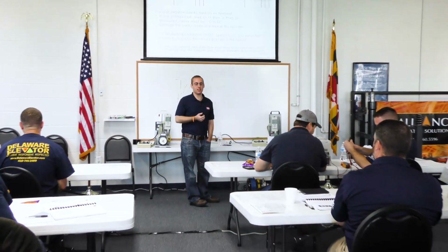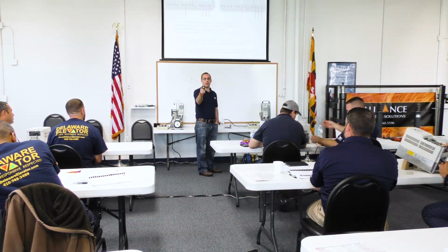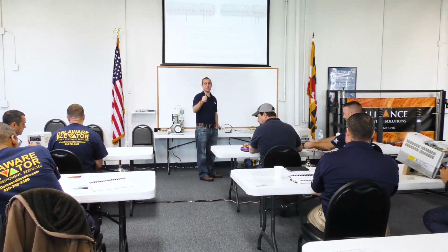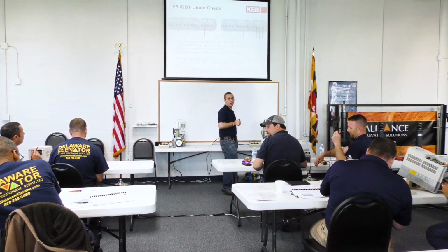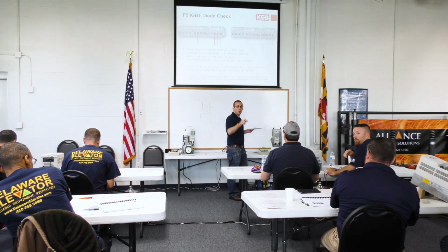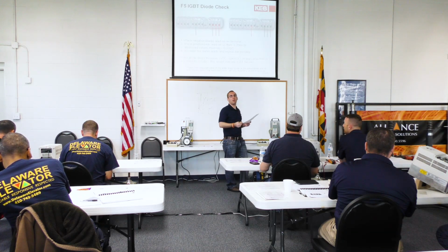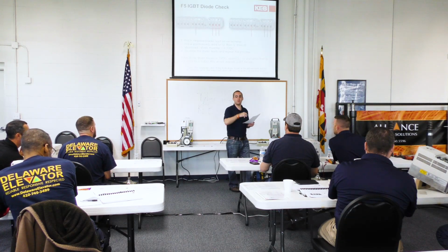There should be some shorts out there. Oh, I hear a short there. What phase is it? U phase. What drive number do you have? If you look right next to the keypad. No. 1. Yep, the U phase is bad on that one.